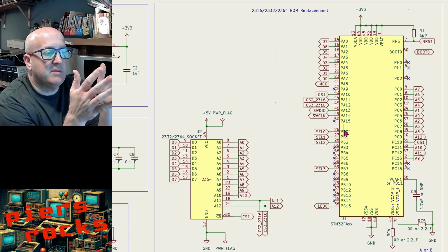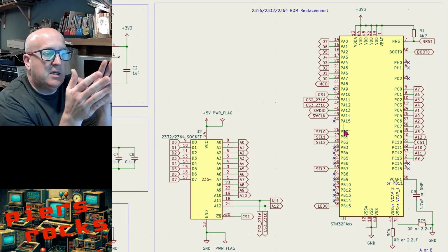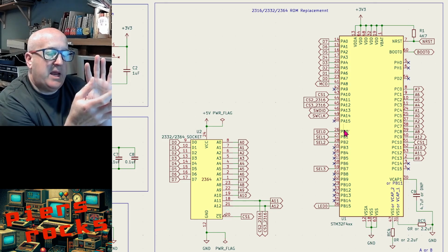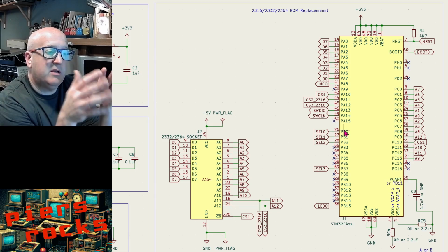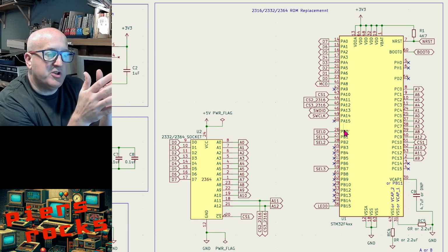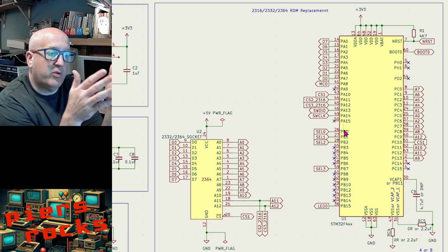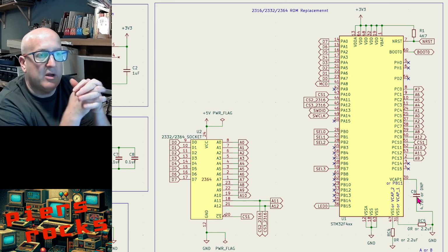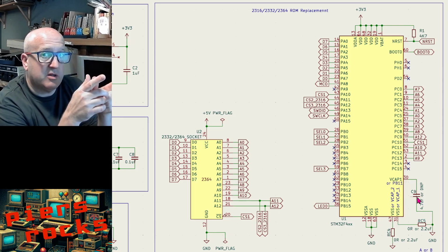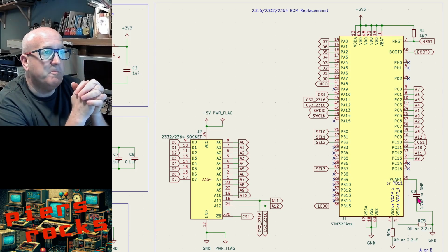One other thing to note in this schematic is that there's some slightly different pin assignments on the F405 and F415 compared to all of the other F4 variants, and those are the VCAP and VSS pins are slightly tweaked. The schematic here is for revision E, and revision E onwards supports both types of F4 chips. You just have to populate RC4, RC5 and C9 differently depending on which you're using. Haven't yet verified this hardware design though, as of recording this video.